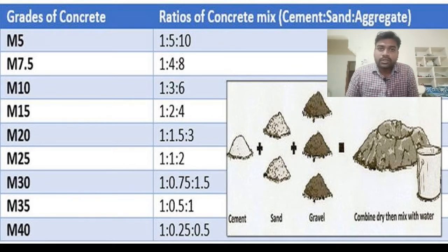So basically what we do is mix it thoroughly, so that the concrete which forms is slurry type, in the form of smoothly moving like a fluid. It should not be completely fluid, but a little bit of friction should be there inside whenever we pour the concrete.